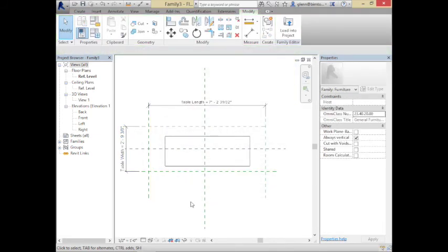Okay, are you with me so far in terms of trying to set up some dimensions? I've got these dimensions, and they're going to push the green lines around. What I'd love to do is go one step further and have those dimensions push the edges of the real surface around. How I do that is with my all-purpose align tool.